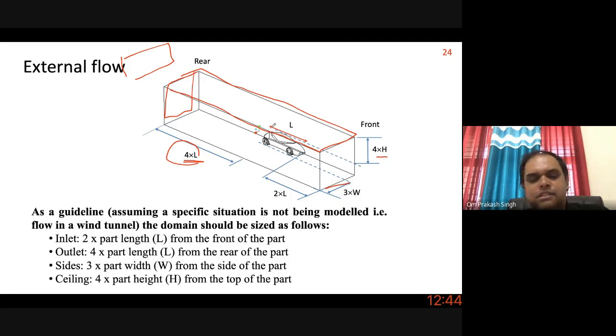In no way. So the simple way is to avoid that: there should not be a drag. It should be a free surface. So just put a slip boundary condition on all the walls. Then you will see in the simulation there will not be any velocity gradient.